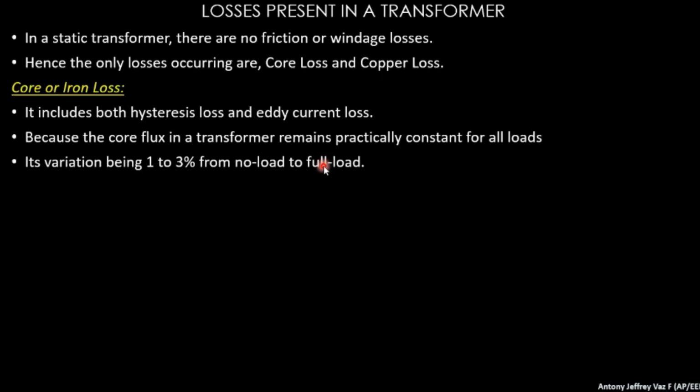What is hysteresis loss in terms of physics? You can say magnetizing a material and demagnetizing a material have different curve forms. Once you magnetize a material, the curve will be in one form, whereas when you demagnetize the material, the curve takes a different form. So while magnetizing as well as demagnetizing, the losses are different. This transformer loss is due to hysteresis.